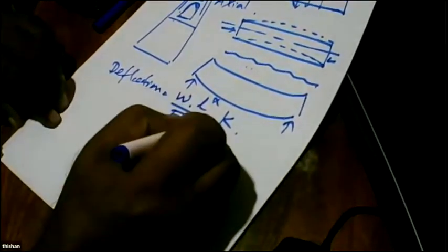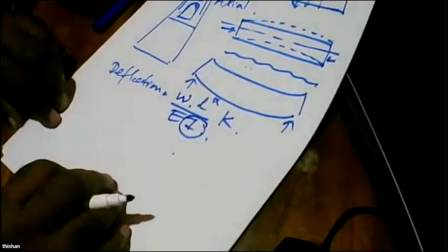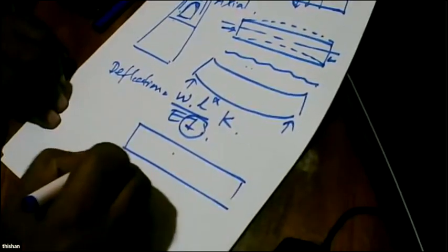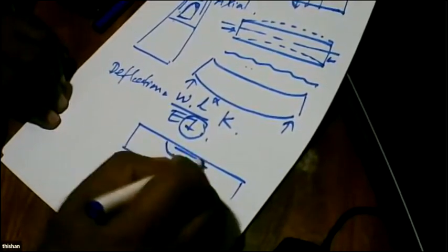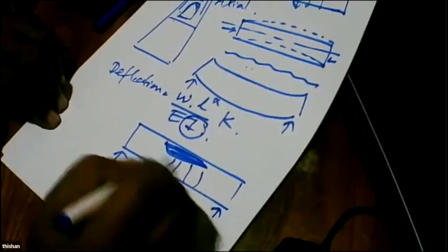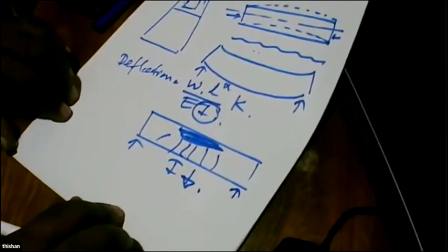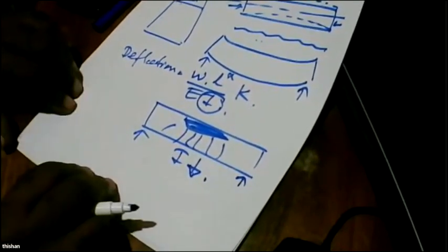So if you look at I value, because the section is not cracked, the I value is high. Whereas if you have reinforced concrete, under the same situation, here you get compression, below that is cracked. So the I value is low. Whereas in this section, I value is high because it's not cracked. So the deflections will be much smaller.